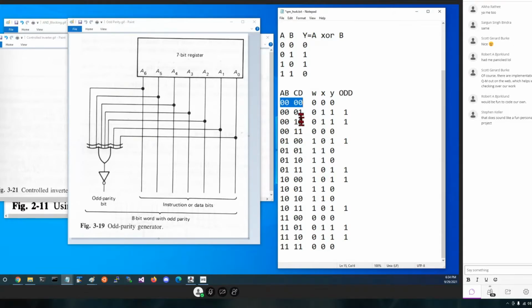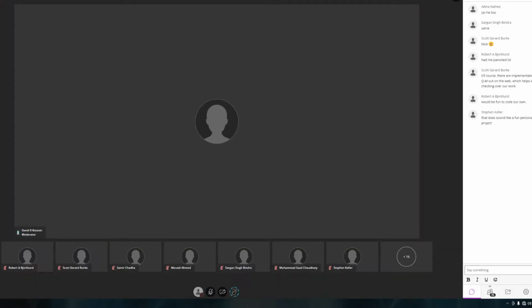4 we don't. So by using this as though it were just a 4-bit, where we only had 4 A's coming in, passing it through an exclusive OR, and then taking the combinations of each pair and passing them through a 2-input exclusive OR, we've generated something which you could use to generate odd parity. Now, in our case here, because we use 7 instead of 6, we need to invert it one more time to actually get the odd parity.